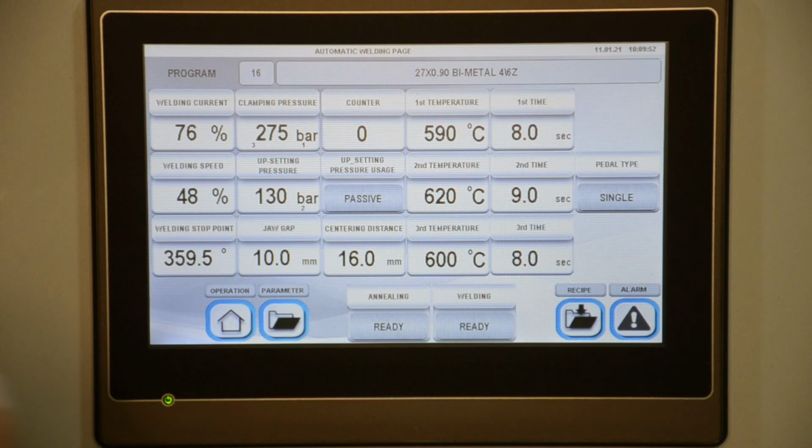In case some alarm appears on the machine, after repairing the alarm it will be good to do referencing again. You can click the reference button, then click the start button. While there is a yellow bar on the screen, please keep your arms out of the machine. When the referencing is over, the home page will appear on the screen and you can continue to work.